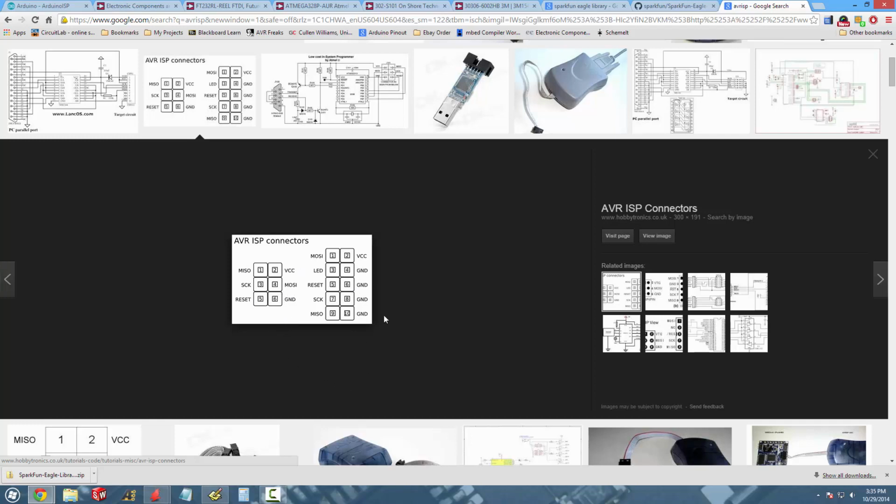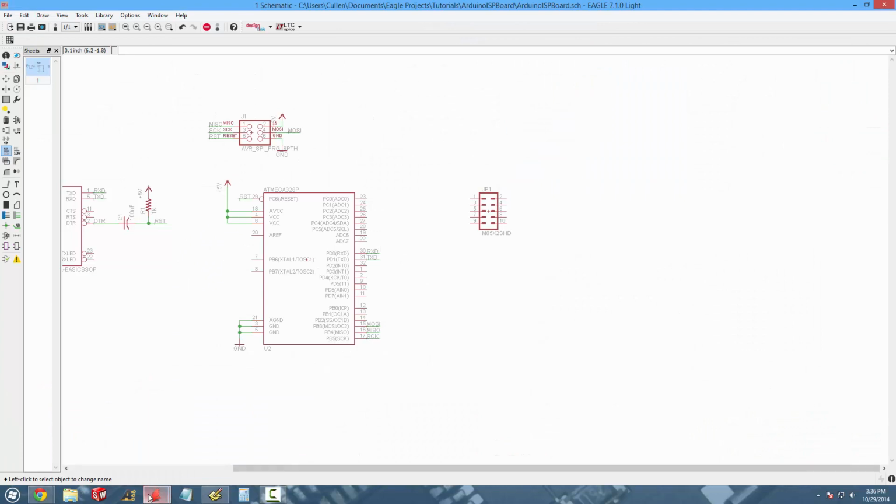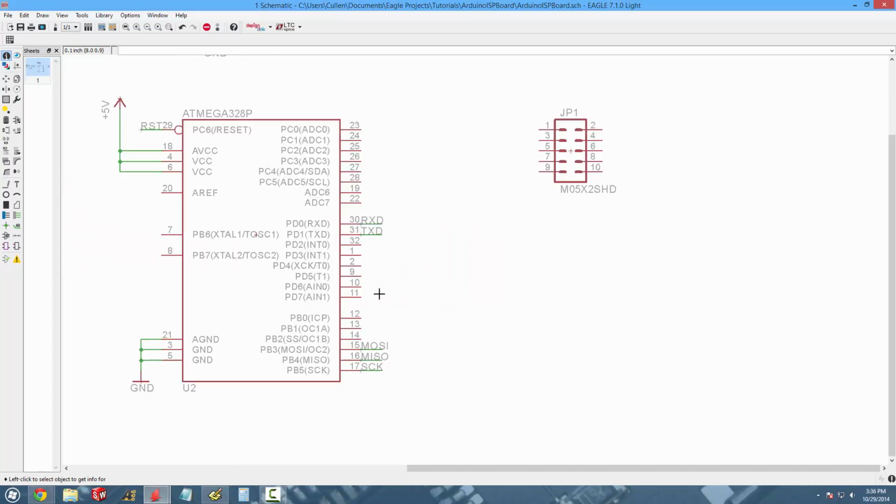But we're going to put both of them on the board so that the user can connect either or. It's a little neater, looks better, but you would probably be using this 6-pin most often. And I like the shrouded ones for this design. If you go into the info here, see how this is shrouded? It'll look much better. Won't slip as much.